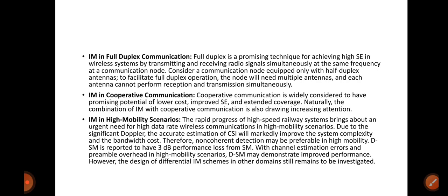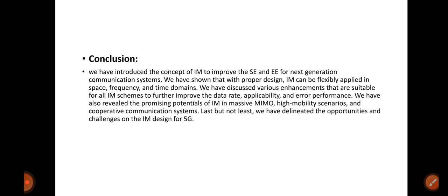DSM is reported to have a 3 dB performance loss relative to SM with channel estimation errors and preamble overhead. In the high mobility scenario, DSM may demonstrate improved performance. However, the design of differential IM schemes in other domains still remains to be investigated.